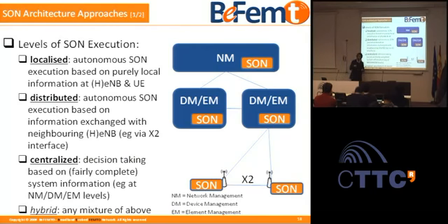If you see that one of your cell users has a very weak field strength, which you get with the link quality indicator, you go down in modulation index. This is a local decision you want to take. There's no need to involve a central entity placed somewhere 200 kilometers from here. That's something very local. You can decide right there, and this is done today.